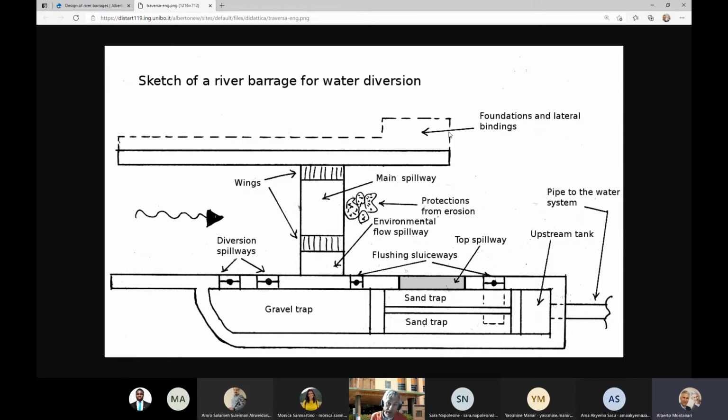So this is why when your water withdrawal is placed, for instance, at the closure of the mountain catchment, in a location where the downstream slope is very mild, we use open channel flow. When instead there is a water withdrawal that is placed high in the mountains, we use pipe flow.